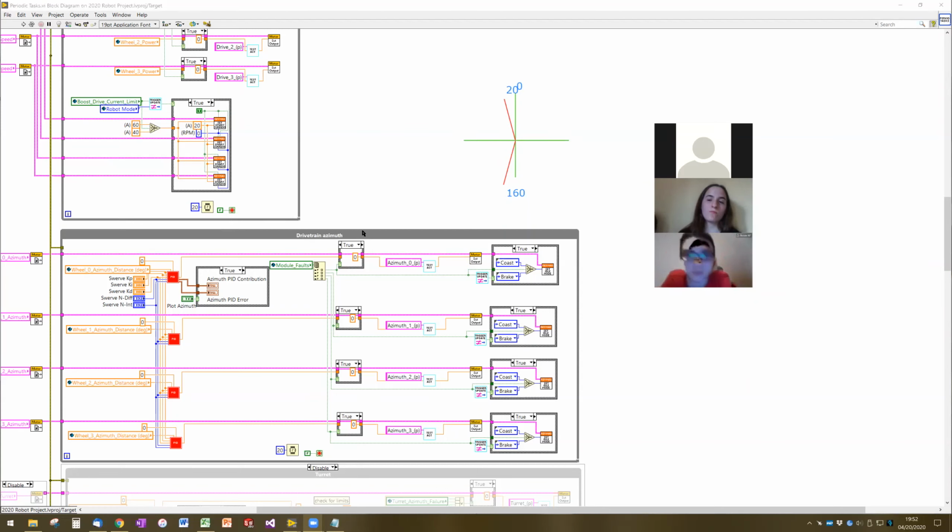Does anyone have any guesses or remember why we can't just put 160 degrees into the goal and put the encoder value into the process variable, why we have to do this angular distance portion for it? Because angles wrap around. So the angle values that seem far apart are actually close together in the circle?